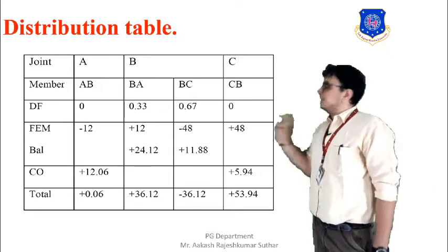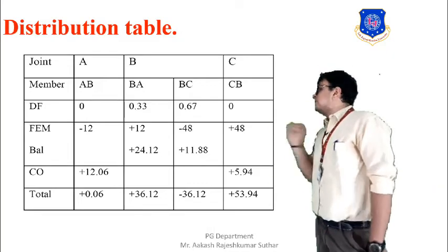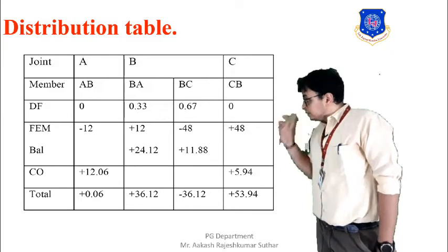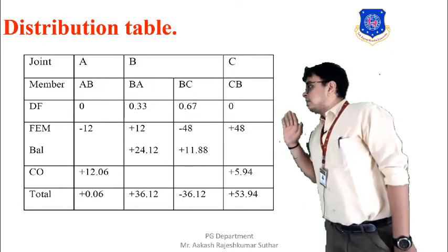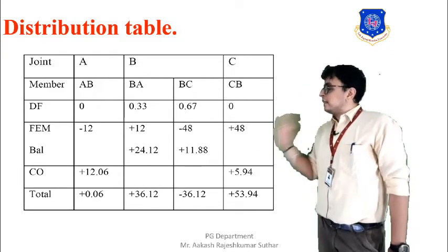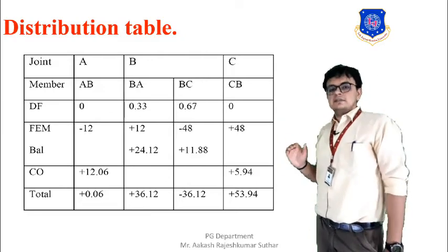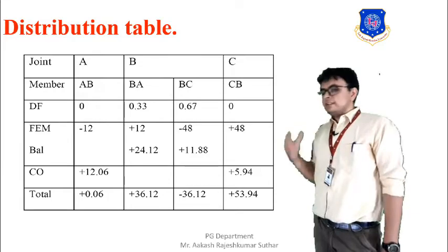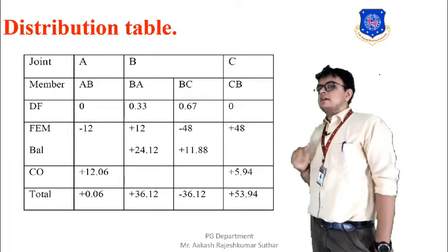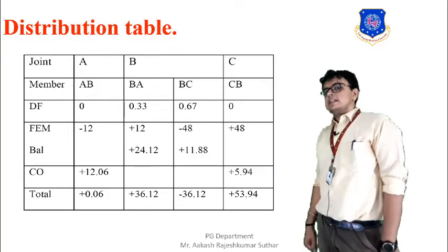we are getting the same value but the sign is different, and that is the signal that shows us our calculation is proper, because everything is nullifying. Both the members' moments are compensating each other, so we can say that our joint will be in equilibrium.